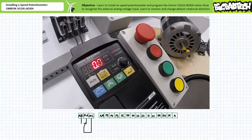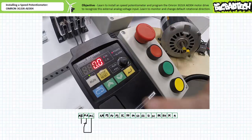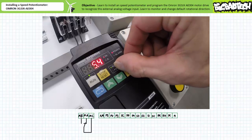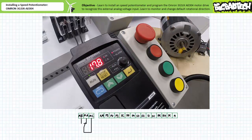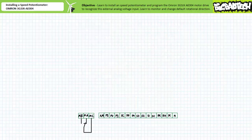In the previous application examples featuring the Omron 3G3JX-AE004 motor drive, we use the frequency adjustment knob in the digital operator group to directly vary excitation frequency. While suitable for some applications, other applications may necessitate control of rotational speed at different remote locations using an external speed potentiometer. First, we need to wire up the speed potentiometer to the appropriate accessory terminals underneath the removable faceplate.